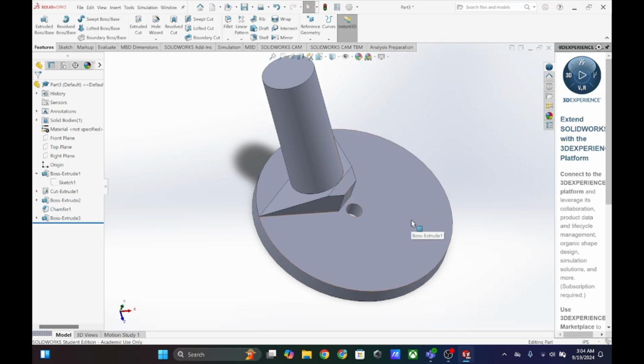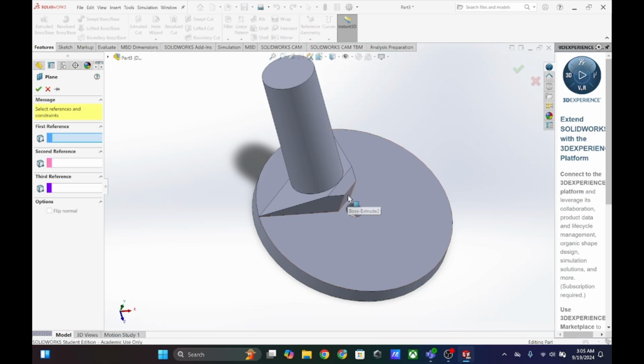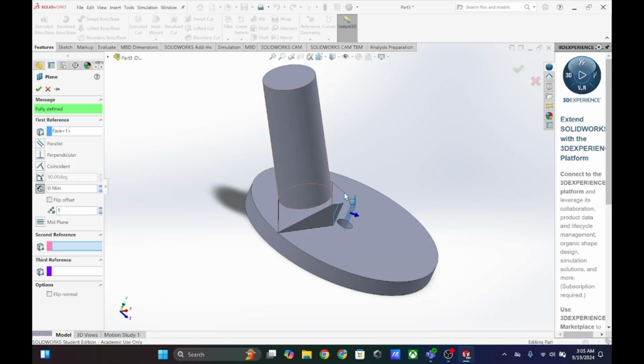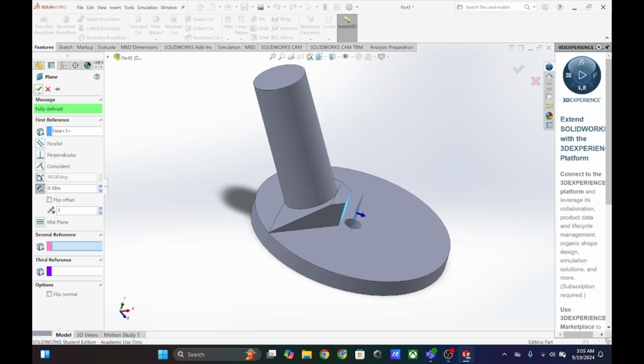We are going to install another one. Imagine using an actual microscope, you can rotate the magnification. So we're going to put 2 magnification settings on here. Let's add in a reference geometry, a plane, from this flat surface that will go out 0.18 inches, and that will place us directly in the center of our shape.